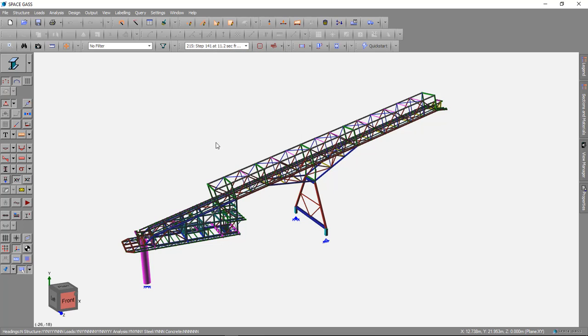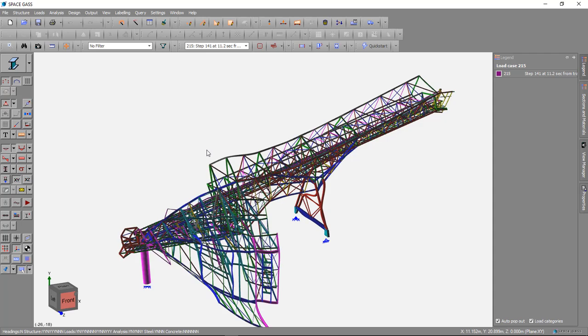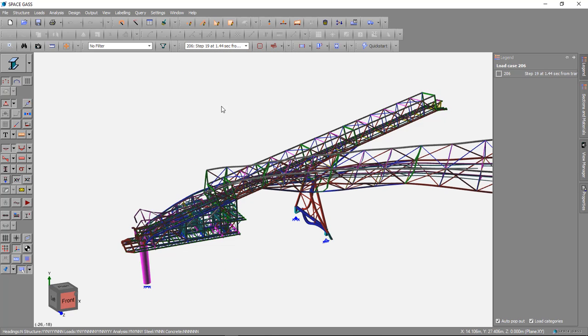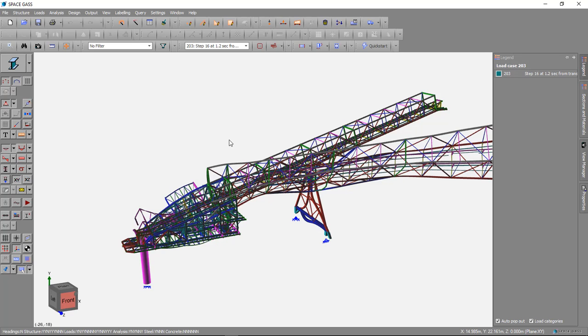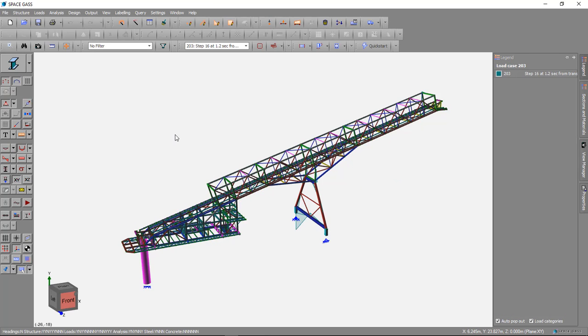results. So if we look at one of those, turn on the deflections, and I'll just change the scale a bit. You can see that's one load case. That's another one. So these are just snapshots in time at various points through the 40-second duration that we analysed. And you can also get bending moments and shear forces and so forth, as you would normally expect.